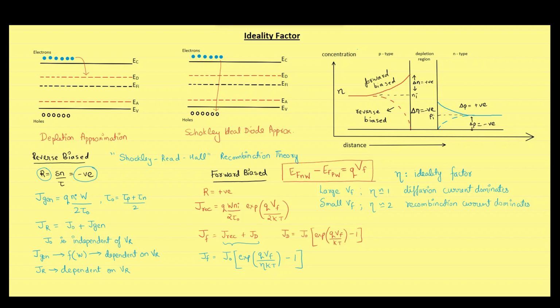You may study the same phenomena in BJT as well, and actually the use of ideality factor is more common there. In diodes, generally the value of ideality factor is taken as 1 unless and until it is provided in the question. While reading books, you may get two statements which are quite contradictory.